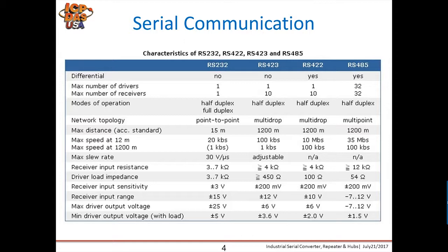Typically, serial is used to transmit ASCII data. Communication is complete using 3 transmission lines: ground, transmit, and receive. The port is able to transmit data on one line while receiving data on another. This is referred to as full duplex transmission. Other lines are available for handshaking, but are not required.